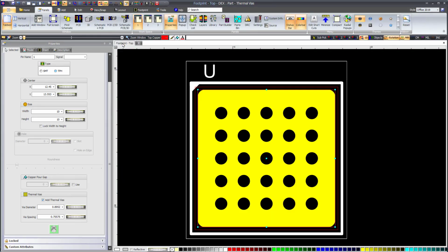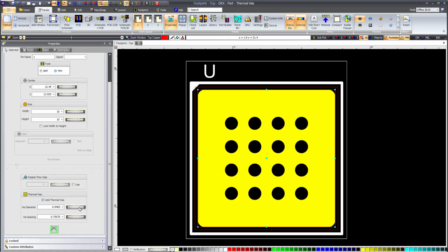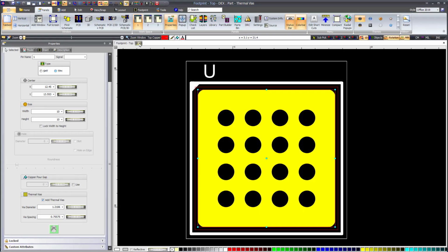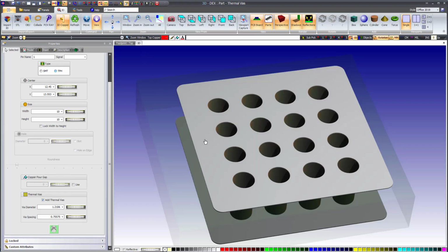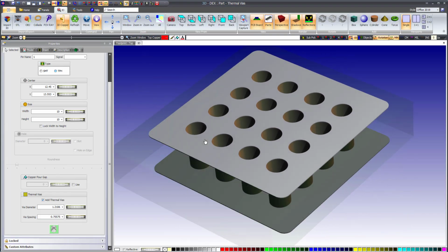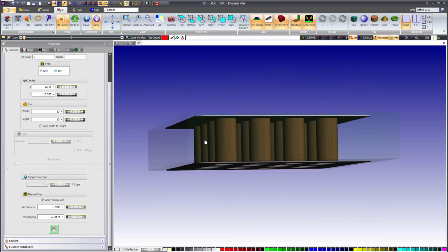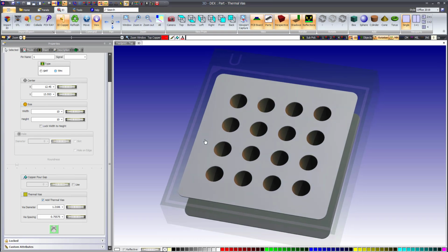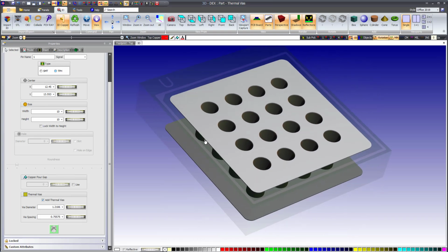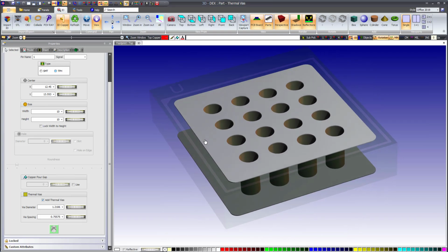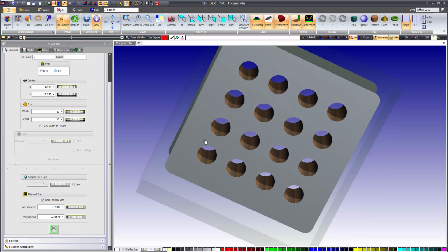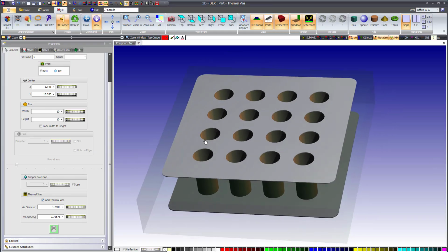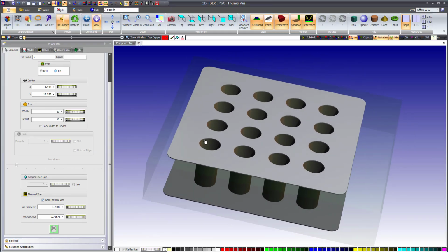You'll often see them used underneath components that generate significant amounts of heat during operation. Many modern electronic components produce heat as they work. Examples include voltage regulators, power transistors, LEDs, microprocessors, motor drivers, and other high-power devices. While the copper on the top layer of the PCB can help spread some of this heat, it is often not enough on its own to keep temperatures under control. This is where thermal vias become extremely useful.